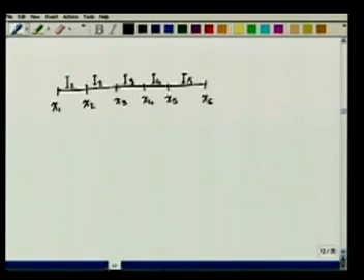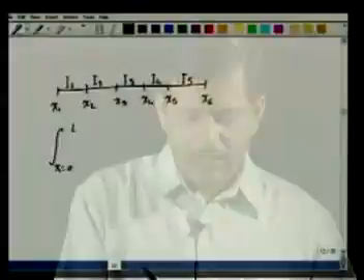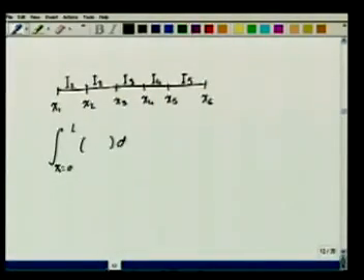What we can do is break up these integrals from the weak formulation into a sum of integrals over each of these elements, because the integral from x equal to 0 to L of any expression dx is equal to the integral, in our case, of x1 to x6 of that expression dx,